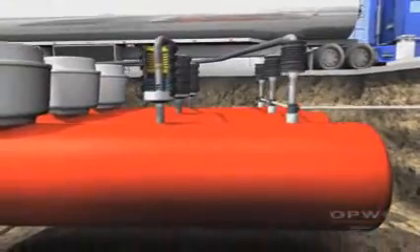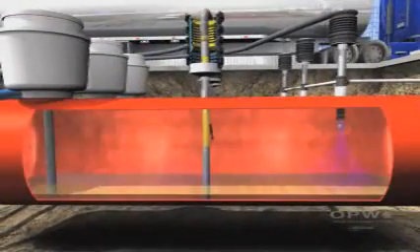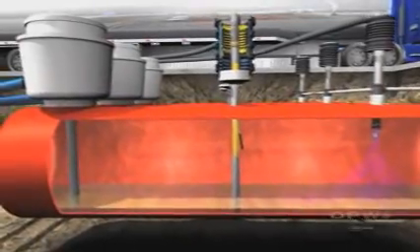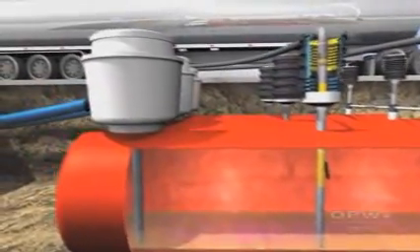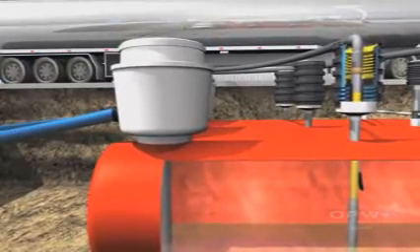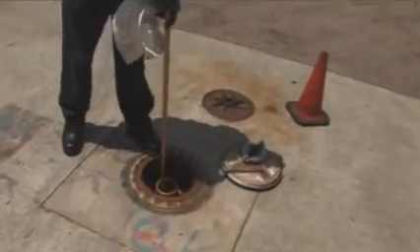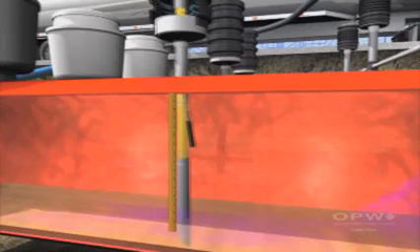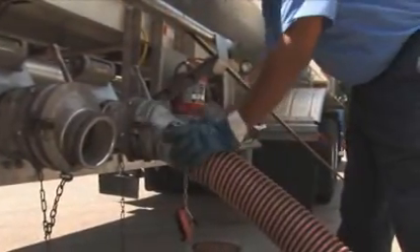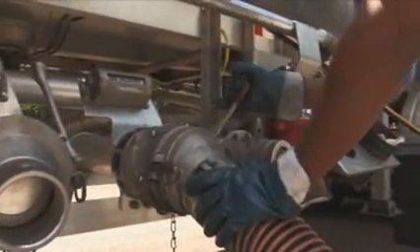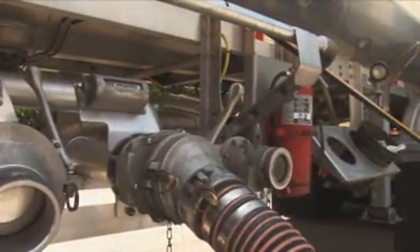For pipes installed on or before November 9, 2006, fill pipes or drop tubes should extend such that gasoline discharge occurs no more than 12 inches from the bottom of the tank. For pipes installed after November 9, 2006, gasoline discharge should occur no more than 6 inches from the bottom of the tank. Owners must also provide documentation that the gasoline level never falls below the 12 or 6-inch fill pipe discharge point. Level 2 regulations may require larger facilities to install equipment that will help reduce the amount of vapors generated while gasoline is dropped from the tanker truck into the gasoline dispensing facility storage tank.